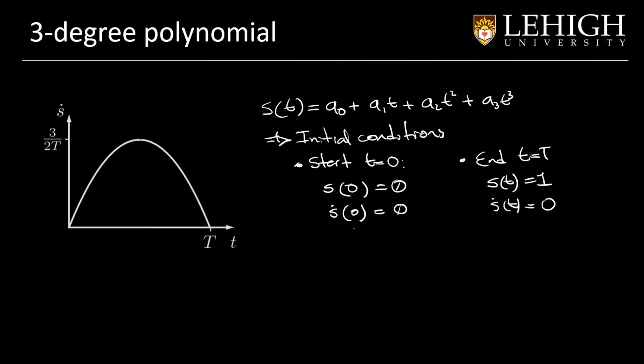trajectory, right? We can see in the curve on the left that the peak in the velocity will depend on the inverse of the duration of the trajectory. That's why if we want to flatten or make this curve smaller, we just need to increase the duration of the time.